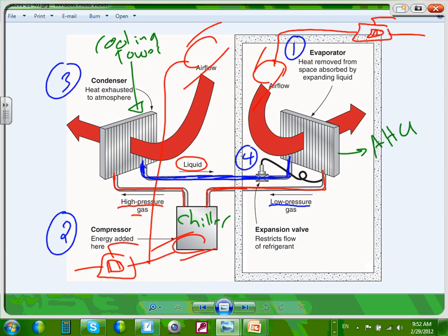And instead of refrigerant pipe that they're pulling, because you can't pull refrigerant, guys, 500 feet away inside the whole building. Instead of refrigerant in a smaller system, what they do is chilled water. Yeah, in a larger system, they chill the water. So the whole cycle happens here, they chill the water here, and then they send water to circulate into the cooling tower, as well as the condenser with the evaporator, in a slightly different way. It's not exactly the same way, but similar.